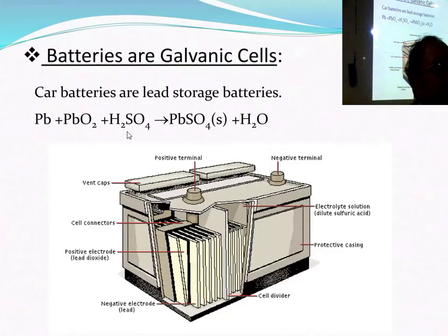And another plate is there, that is called lead oxide plate. Oxide is a powder, so you cannot make a plate out of that. So make a paste out of this lead oxide powder, and that is applied into this lead plate grid to make lead oxide plates. So two types of plates are there. One is lead plate and one is lead oxide plate. Lead plates are just the grid system, and lead oxide plate is made of the same grid but coated with some lead oxide paste.